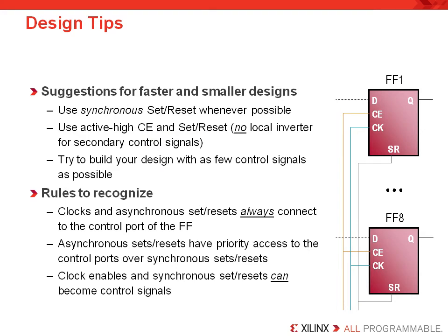Suggestions for faster and smaller designs include using synchronous set and resets whenever possible, using active high clock enable and set and reset signals. Note, no local inverter for those secondary control signals exists. Try to build your design with as few control signals as possible.